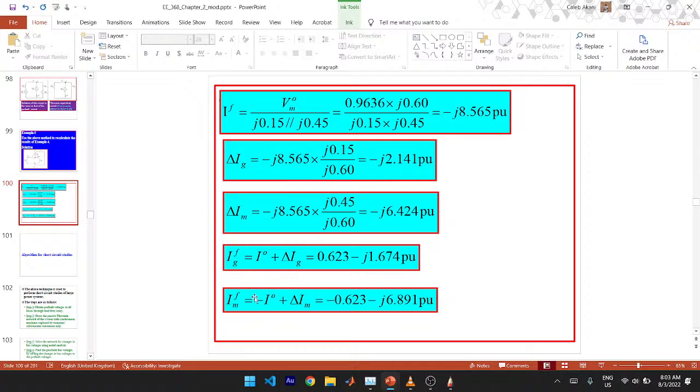Yes, so that's how come these formulas are here. It's just because of the direction of the actual diagram compared to the Thevenin equivalent direction of the current indicated. So that's how we have it. You check, these are in per unit, and they are the same. So if you want to find the actual, find your base and multiply by this.